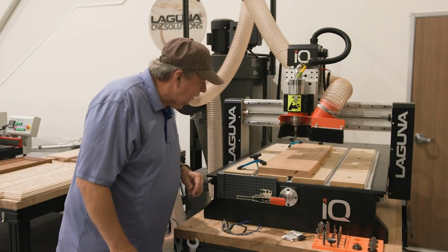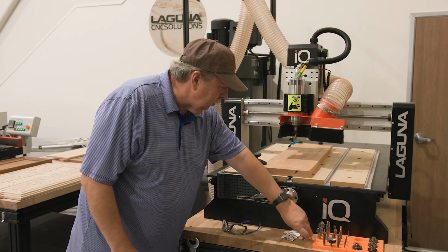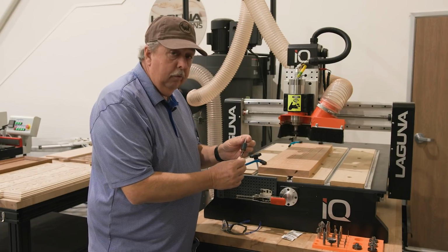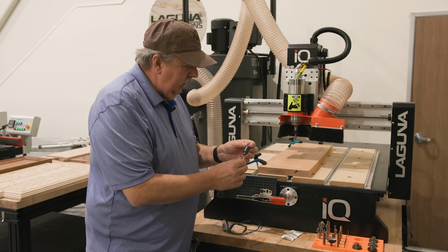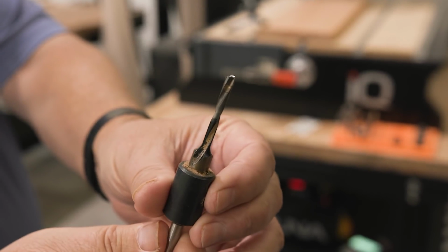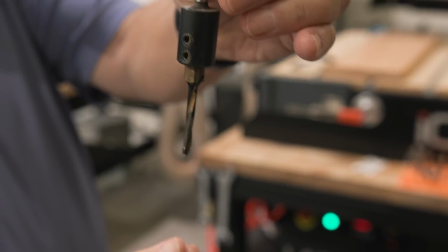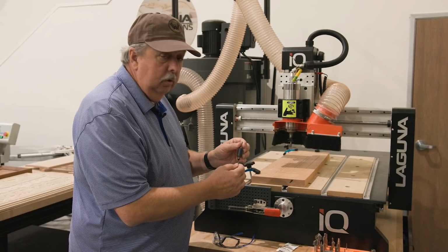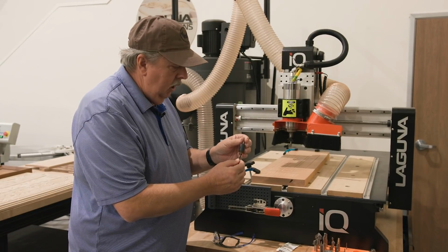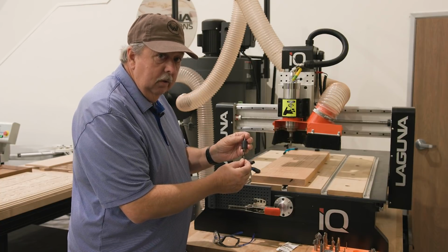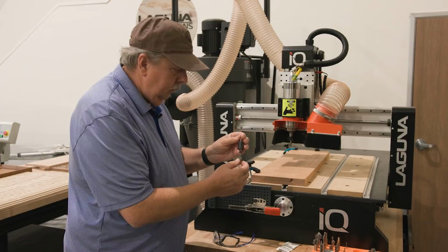Looks pretty nice and clean. Now we're going to switch over to the next bit for this carve, which is the hole drilling. We're using this specialized core drilling bit for CNCs, and that will make the peck drilling process a little better. You can do this either with a core drill bit, which is what this is, or you could use an end mill if you wanted to. I prefer using the core drill bit. It has less heat and less friction than using a regular end mill.